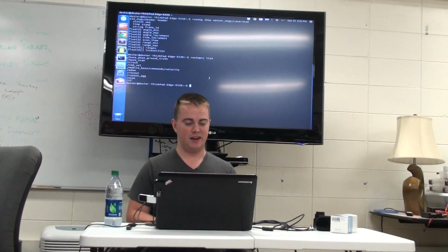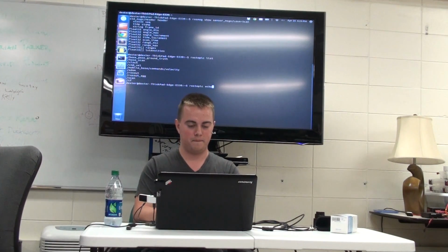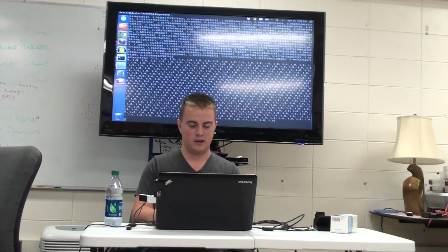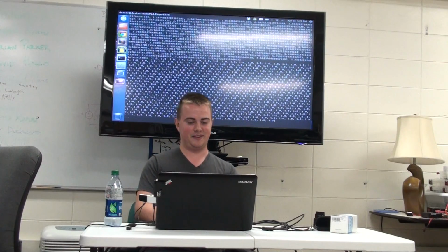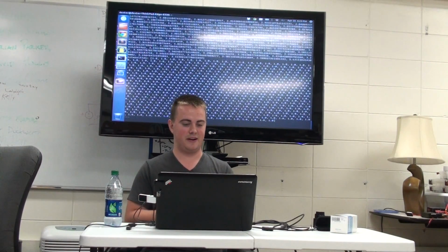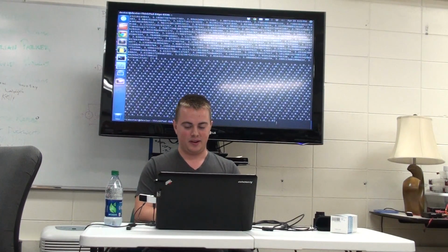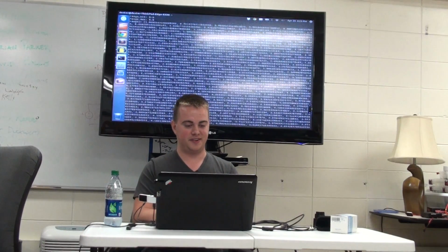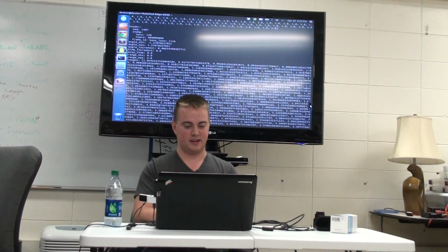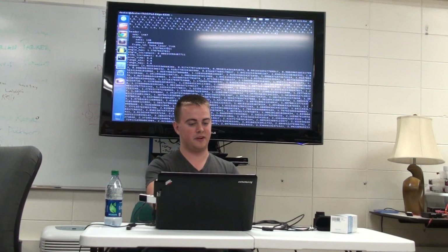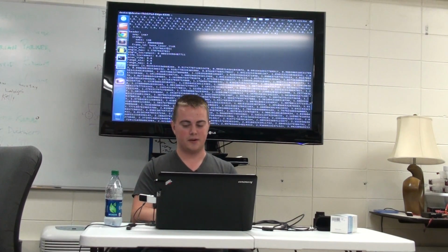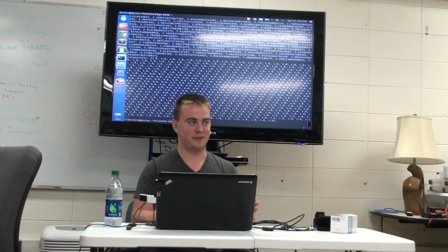So for example, if we want to see our laser scan data, we can say ROS topic echo, and then base scan, and that's the output we get. So it's publishing laser scan data very, very quickly. And so we're going to kill that. What we get is an array of intensities and then an array of distances from the scanner where it's detecting things, as well as our constants that we defined earlier. So we can see that's clearly working. That's clearly publishing things.